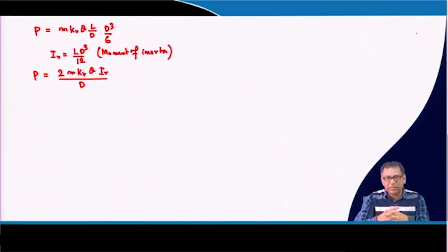So, the total horizontal force due to the soil reaction, because the well is rotating, and then when it is rotating, the soil will give the reaction. So, that total reaction force of the soil is P, and that P we have determined, and because of that P there will be a friction between the soil and the side wall, and that friction is P into mu dash.